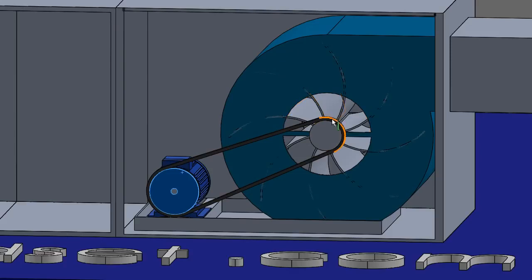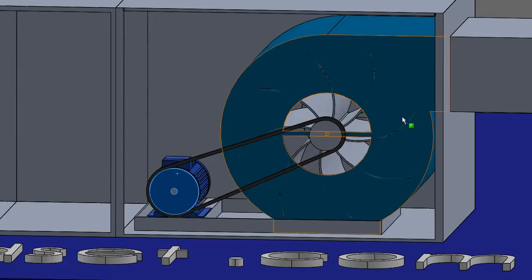So as this occurs, it's following along the curve and it's being shot off, and this is pushing it, and as that comes around to say here, it's at full swing, and it gets thrown out, and there's more air coming around this way. It's being pushed, and so that builds up the pressure, the static pressure in this duct here, and that drives all that air out.